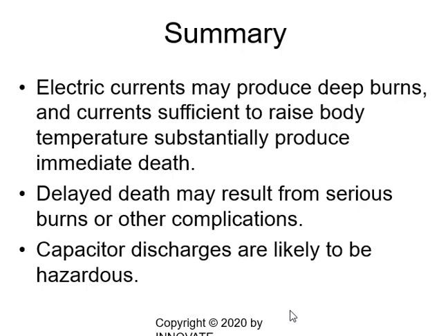Now, we did not talk about the electric components in electric circuits, like capacitor and inductor. Both of them are very dangerous, because they may charge, and their discharge is likely very hazardous. The interesting thing is, if you have a capacitor and inductor in one circuit and you reach resonance, it could be quite dangerous, because the voltage across the capacitor and inductor could be extremely high at resonance or close to resonance.